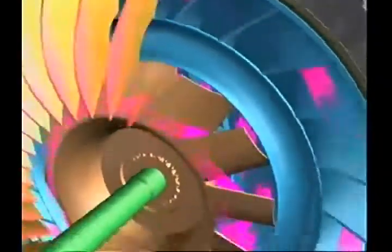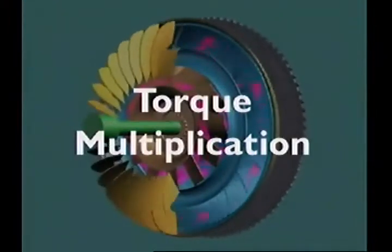The fluid re-enters the impeller at high velocity in the same direction as impeller rotation. It strikes the back of the impeller vanes with considerable force, giving up energy to assist the engine in turning the impeller. This provides torque multiplication.